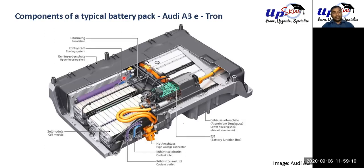another Audi battery. Similar thing, just in a little bit more detail. Here as you can see, as I was saying, there is a layer of insulation. There is always insulation. Then there are these cooling systems. These are plate type cooling. This is a flat plate which has cooling channels built into it, something similar to those that you see on a transformer. These are different modules, and in between the modules there are these cooling panels.